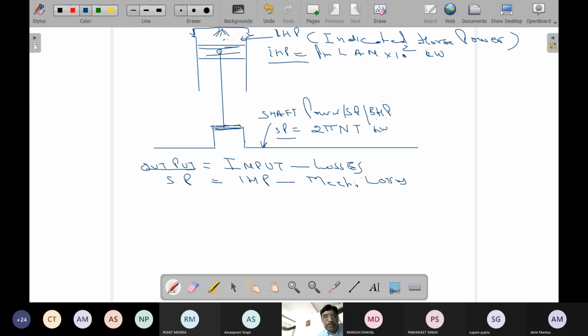And we have a term to indicate efficiency, any efficiency: eta, and writing a suffix here, mechanical, mech. So efficiency is output over input into 100. So we say efficiency is 80%, 50%. Like marine diesel engines, they are giving us slightly more than 50% now, the modern ones, whereas turbines used to give us 29, 30% efficiency.